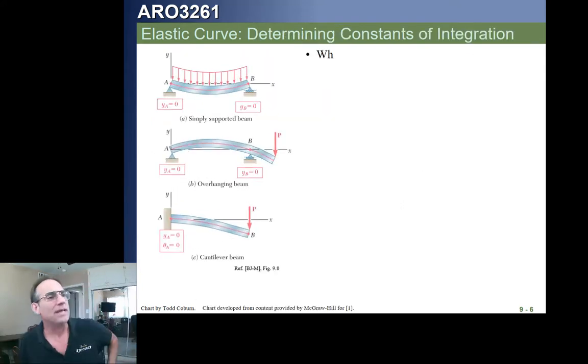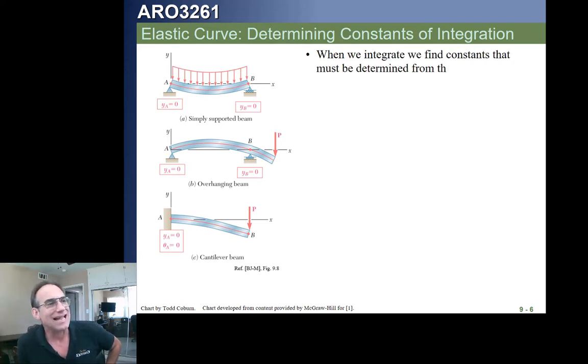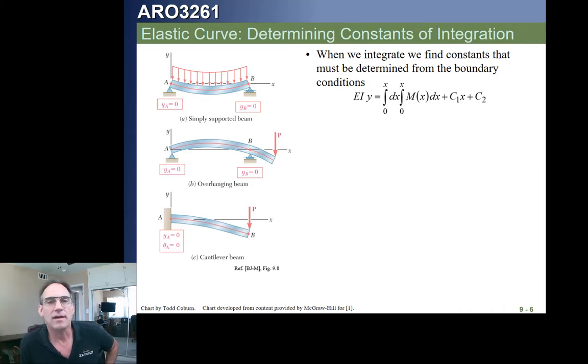All right, so here's a couple beams. We can see the neutral surface here, or the elastic curve. They're shown red in here. Few different loadings. And if we look at those, we see, in this first figure, figure A, we've got 2 pin supports. The first support imposes the condition that deflection is got to be 0 there, and so does the support at B. If we look at figure B, we find the same thing. 2 supports, both stopping vertical deflection, and both of these supports also stop lateral translation. But since there's no loading laterally, we don't actually need to use that. It's not of use for us.